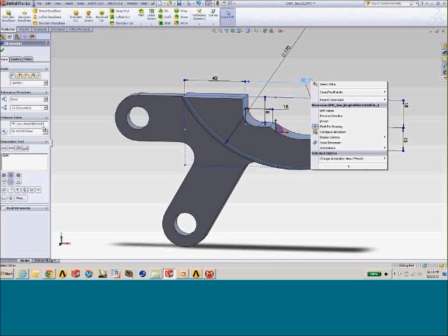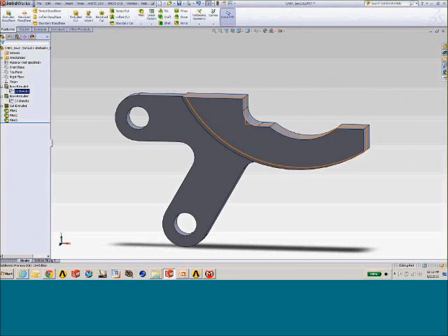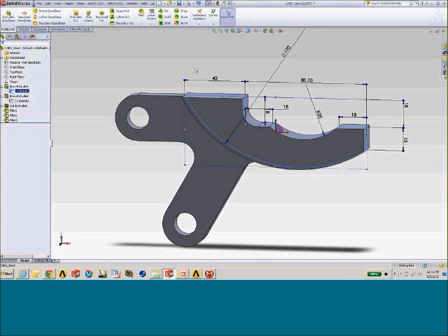Ansys relies on the CAD system to keep track of that because that's where the original features and parameters are linked together. So from a best practices standpoint, it's always a good idea to take a little time, go through your parameters, and give them realistic names, the names that I had shown on the previous page, so that when I'm doing an optimization or a design of experiments on this, I know exactly what that parameter means. I don't have to do any kind of mental gymnastics to figure out what parameter D0 affects in terms of that geometry. So we can go through our particular sketches and our operations.